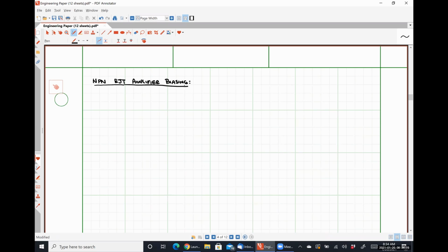All right. So really, what we're going to be discussing in this section is, I think, 4 different ways total in which we can bias our amplifier circuits under the specific constraint that we need to have the circuit with a DC operating point condition that is in the forward active region, because our BJT needs to be in the forward active region in order to be used as an amplifier.